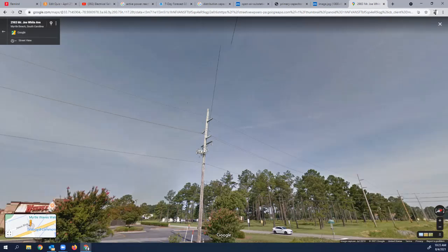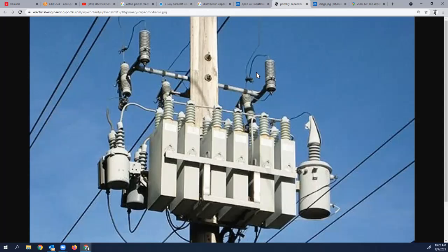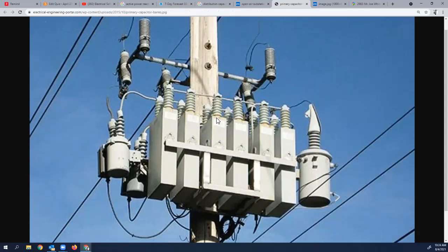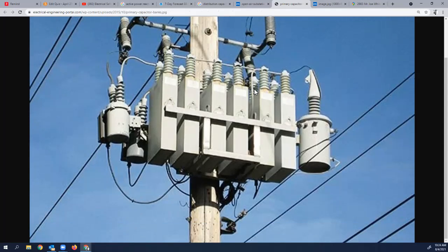The first picture you showed of that cap bank, that'd be more or less along the lines of Duke's construction. And like you said, you could go up there, de-energize it, ground out the bank, and then the guy could climb the pole to assist the guy in the bucket, but it's hard to really change anything out of that rack on the pole. I would agree. It's a climbing nightmare because you don't have much room to work here. Yes, sir. That's up to the company that's going to be telling you what to do. Okay. We'll get into this in just a moment.